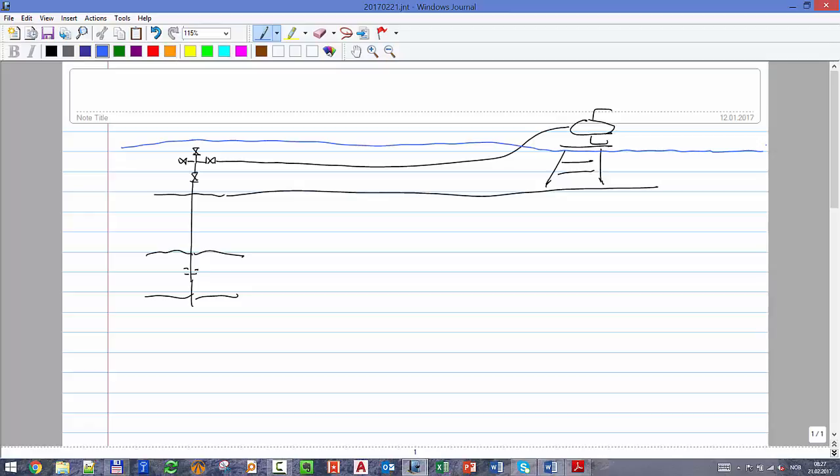Okay, so we said last class that you can choose really any point of the system, any point of interest, and then you can plot on that particular point its standard conditions rate. And you can plot at that point the available pressure curve, calculated co-current. We calculated from the fixed node, the pressure node, which is the reservoir pressure, all the way to here. And that's going to give you a curve that looks like that. That's the available pressure curve.